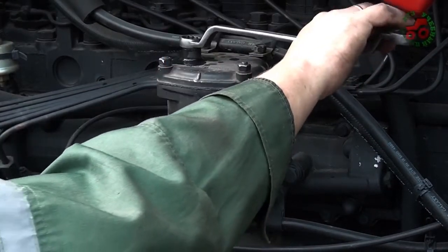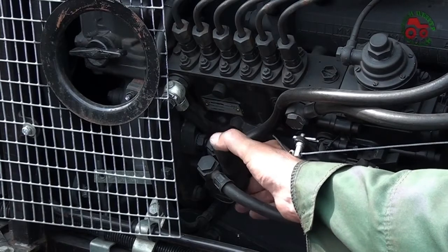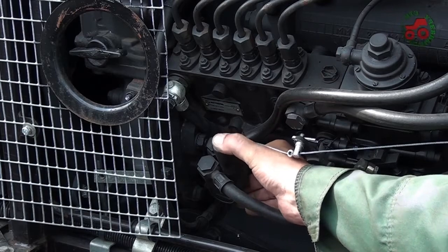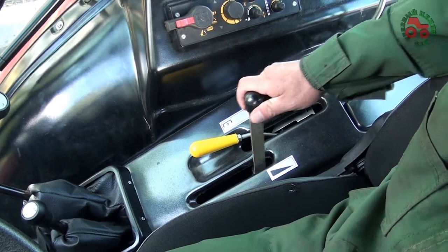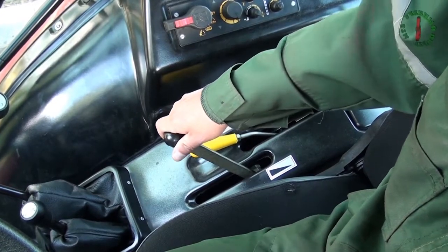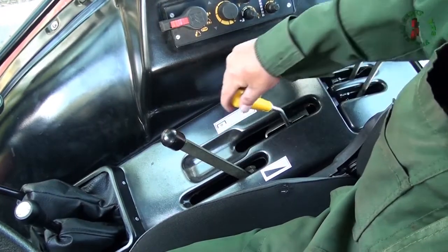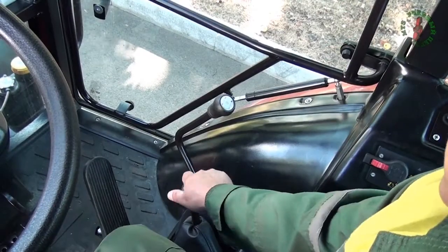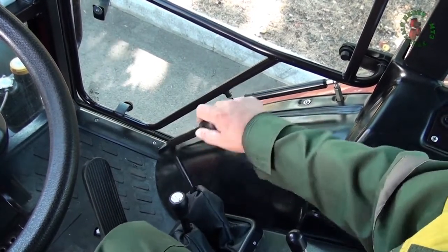If required, fill in fuel and bleed the fuel delivery system to remove air. Set the fuel feed control lever into medium position or into a position corresponding to a minimum fuel supply of the engine, depending on engine model, and the PTO handle into brake position. Set the gearbox levers and the range shifting lever into neutral position.